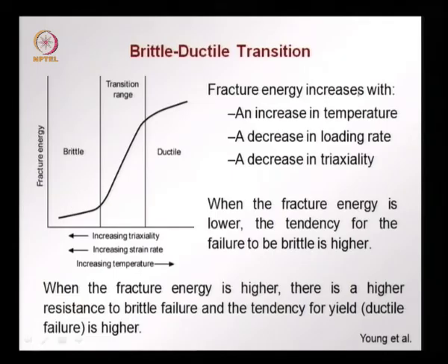Fracture energy also increases when there is a decrease in loading rate, that is, as the loading rate increases, a material will have lower fracture energy, it can become brittle. The fracture energy increases as the loading rate decreases. If you load slower, the fracture energy is higher, there is less tendency for brittle failure when you load very slowly. When you load very fast, you see a decrease in fracture energy and a higher tendency for brittle failure to occur.